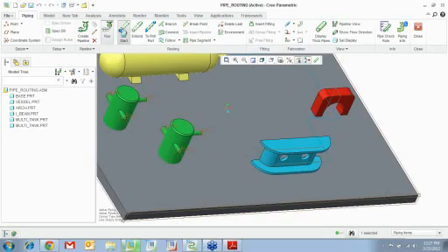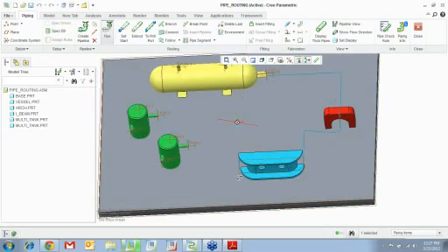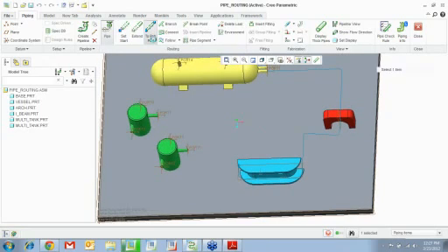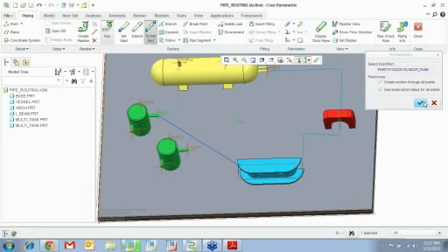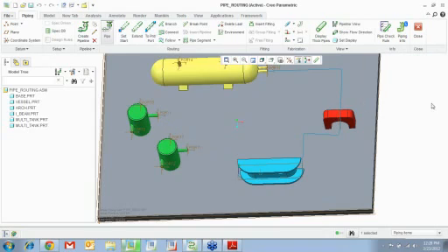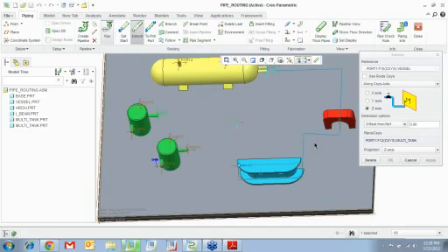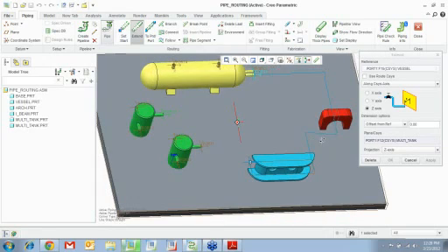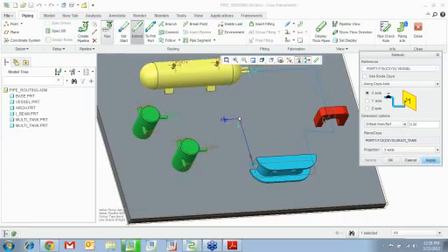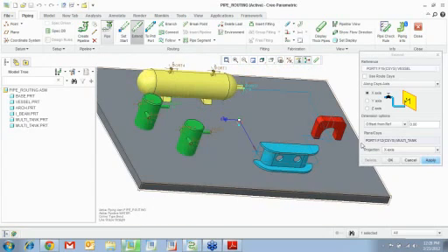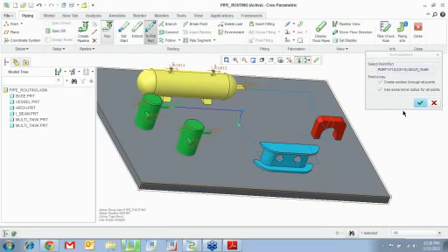All right. So now I'm going to go ahead and say I'm going to start routing from this corner. All right. And 2-point port, and I'm going to pick that port. See what happens? It goes directly to that. Now, if you don't like that, you can always go extend, offset from a reference, pick that in the X direction. You can say it's moving that way. Hit apply. You want to move again in the Y direction. Hit OK, and then say 2-port and pick that.